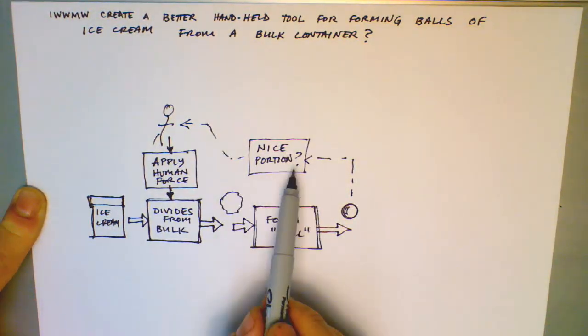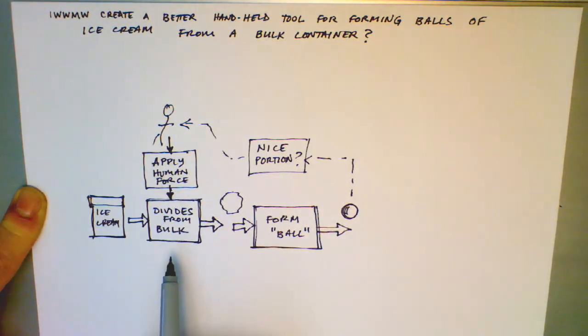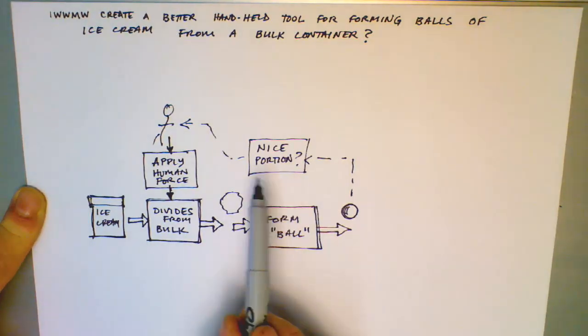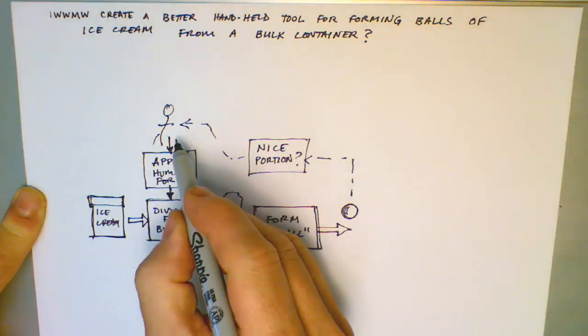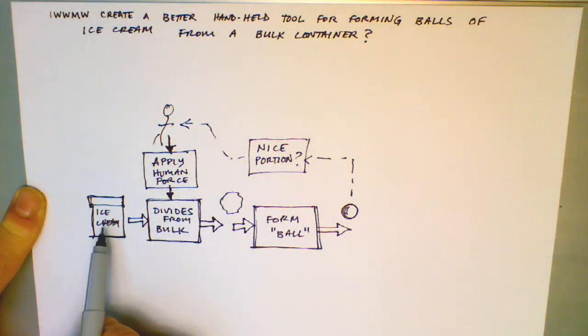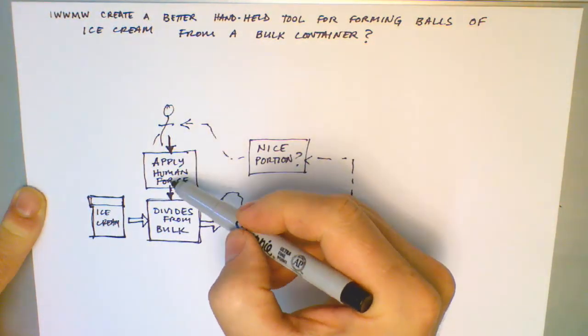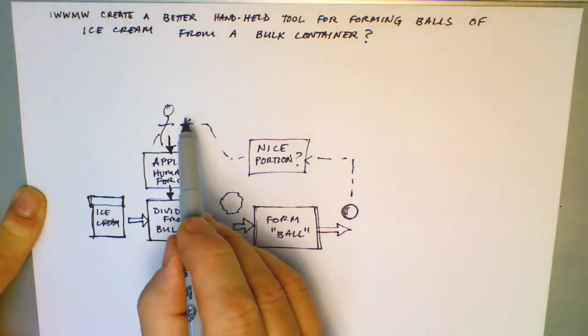All right, so let me first emphasize that function diagrams are not unique. That is, there are many possible ways of decomposing what it is an artifact does by function. This is a reasonable way to do it. I think it's very useful, for most artifacts, to think about the flow of material, the flow of energy or force, and the flow of signal.